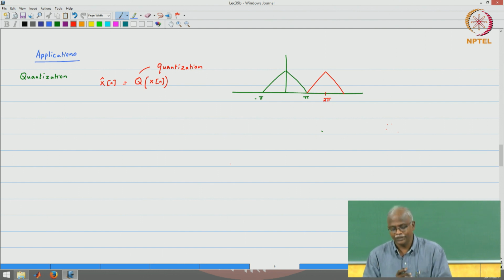Then we pose the question, how does quantization noise enter, and where do I have to keep track of it? We say that quantization noise is something that we cannot avoid when we quantize. I am sure you have gone through the analysis of quantization noise. We say that the quantization noise has certain statistical properties. We will go through them, but by and large the spectral properties of quantization noise are very random in nature, it is uncorrelated, and therefore it is spectrally white.